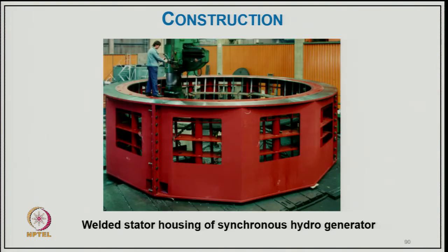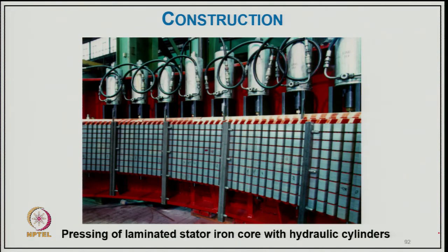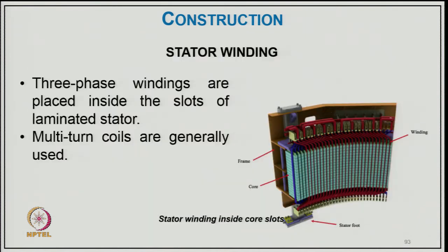Then the welded stator housing of a synchronous hydro generator, as you can see, and then assembling the laminations in the stator frame to form the core. Then the pressing of the laminated stator iron core with hydraulic cylinders.